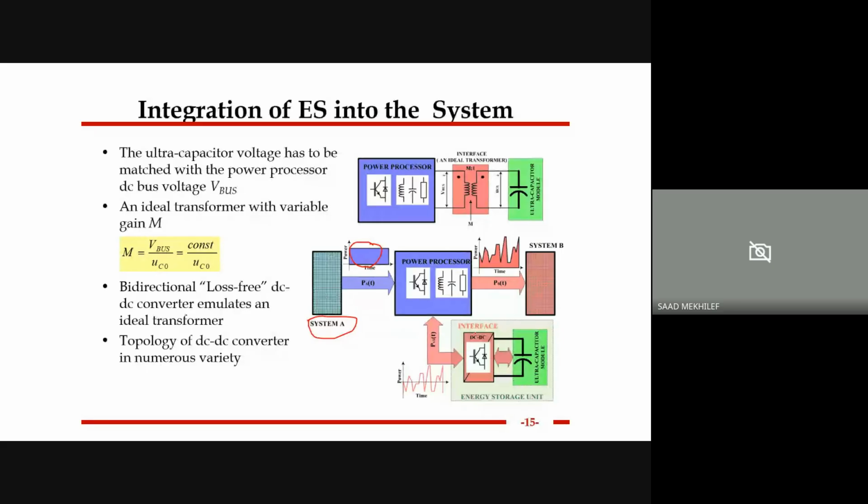Once the storage system's energy or power drops, then the diesel generator will turn on to charge the batteries. So most of the time, the operation is between the PV and the storage, because turning the diesel generators on and off, on and off, leads to a lot of maintenance and is not good for them. And that's why I want to show you some examples. This is what the role of the storage does.